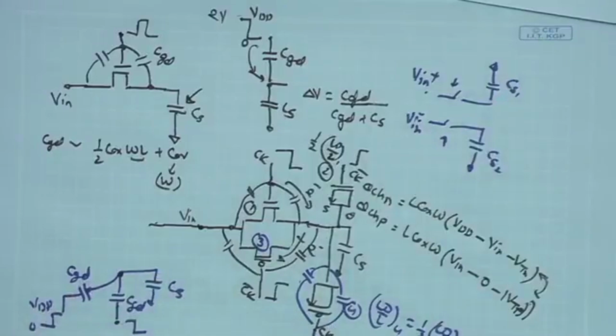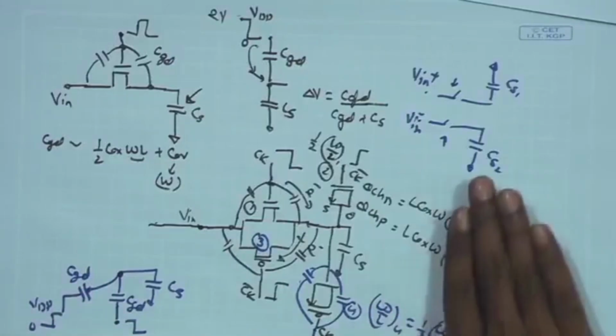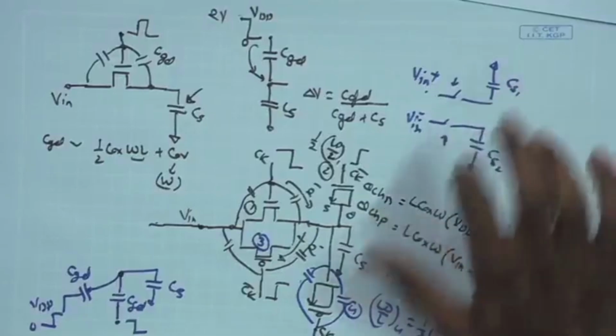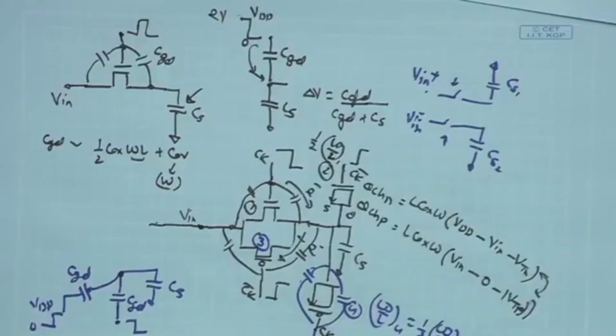So, that is one of the reasons why people prefer fully differential, even fully differential comparators and fully differential ADCs, so that the non-idealities of these switches can be mitigated to some extent, and especially when you go for high precision circuit where the precision becomes a lot more critical, or you need to do some very sophisticated DSP in the digital domain for which you need very precise analog data. For that I would like to cancel out these effects of these non-idealities, but in that case I would like to make even my ADCs or the comparator fully differential.